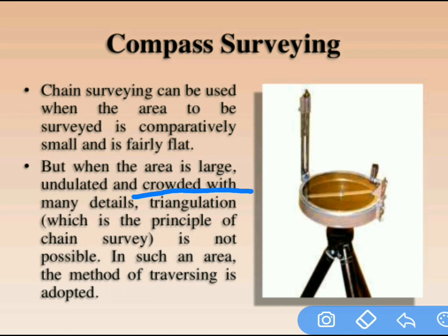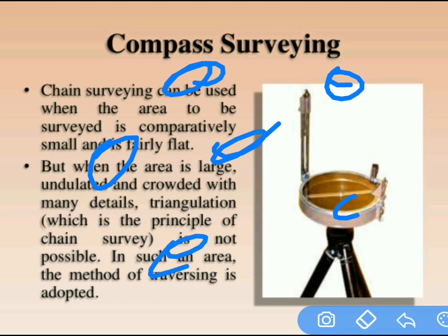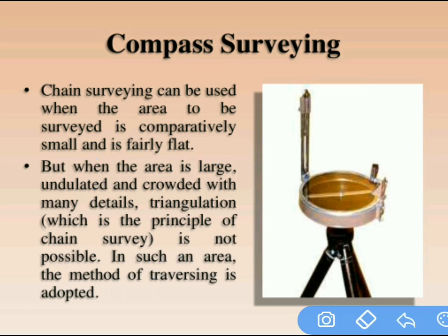Next, if the ground is crowded with many details, meaning the number of objects on the ground is more, then also chain surveying is not suitable. Next, if the formation of triangulation is not easy, then also chain surveying is not suitable.